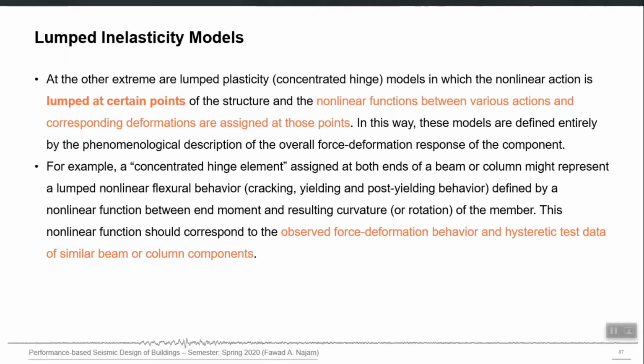You implicitly account for that using some hypothetical elements located at certain locations, right? So that effect is implicitly accounted. The nonlinear functions between actions and corresponding deformations are assigned at those points. So those points are in our control.